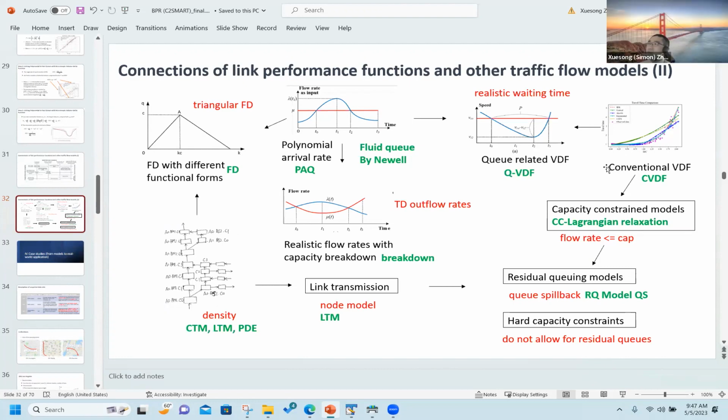Yeah, Ken, thank you for all your wonderful comments, and it's really an honor, first of all, to be invited to present our work here. We do have some thoughts along this line. We look at this figure here, the fundamental diagram. There are many two-way connections. For example, in the fundamental diagram, you have discharge rate as a function of the overall density of the model, and here we are still assuming the discharge rate mu as constant in order to get an analytical form. On the other hand, we see the cell transmission model is able to break this corridor into many small cells.